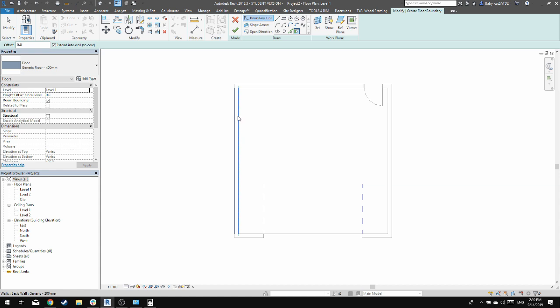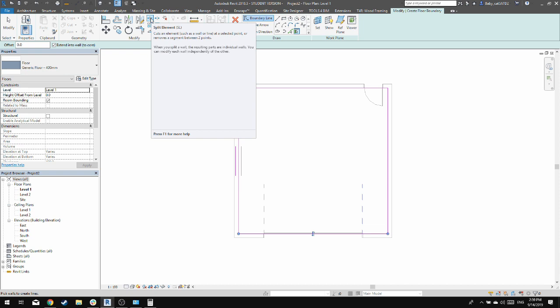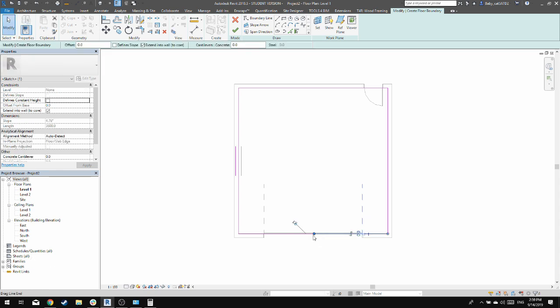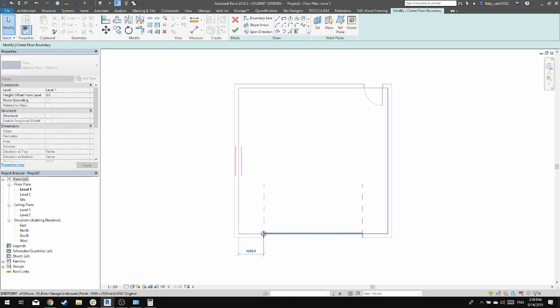Then, if we were using the pick walls tool, we can just simply click on the side of the wall where we want the lines, and click the checkmark. But because I'm thinking we should have a single floor model for both the inside of the garage and driveway, what we're instead going to do is go under the split element tool up here. It's L, and hotkeys in Revit are super important and they speed up your workflow a lot. We're able to split this line, just escape twice, and now we'll see this blue circle, so we can just drag that over to the end of the door, select the other half of the line, and do the same.